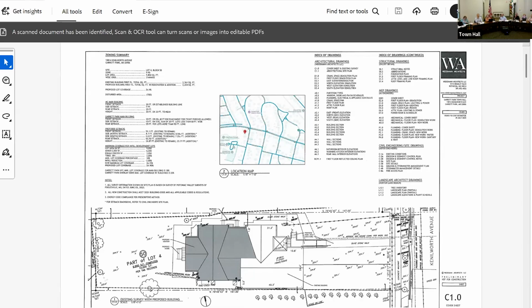I noticed that the windows will be rehabilitated so that they can all open, but the interior storm window, would that be able to be opened and closed? It's removable. I don't know how often you open these windows. Probably never, but I was just curious. Yes, it would be a removable panel, but it's not hinged. We haven't selected the actual one; in a recent historic house that we did, there was a seal, so it was a friction fit and then it could be pulled out.